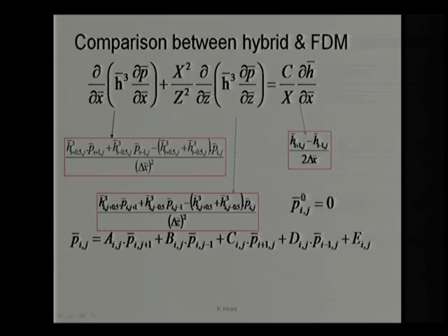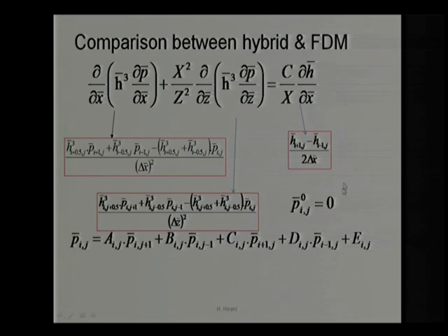Initially, we assume that the pressure at all the nodes is equal to 0, unless we know the pressure profile, or we are able to estimate it by some other method. If we are able to estimate by another method, we can give that as an initial value. However, if we are not able to estimate, then the simplest approach is to assume that all the pressures are equal to 0 at the start, and through iterations it will develop and come to some solution.